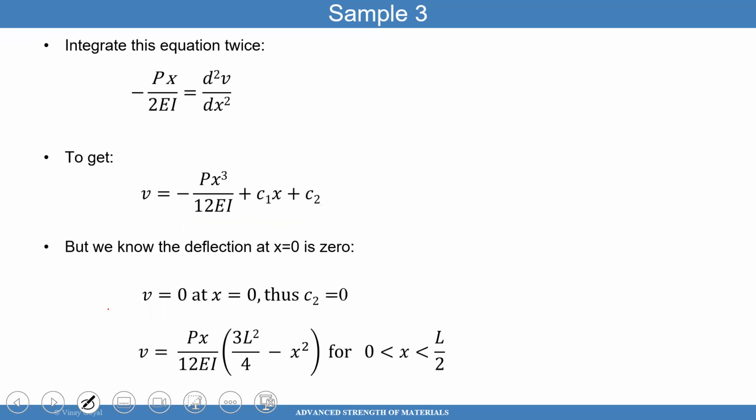I am showing this problem because in industry, some problems can be solved by looking at half of the problem. For example, if I want to look at this Android phone drop, which I don't want to do because I paid money for it, but let's say it drops just symmetrically, then I can just model half of it and put symmetric boundary conditions. We do this all the time with turbine wheels, which have maybe over 100 blades.